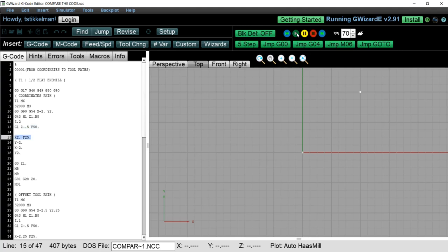Then we do an X 2 inches, so that is the first toolpath to the opposite side of the part. Then the next line, we're moving to Y minus 2 inches. We complete that move, so that would all be line center, but as we discussed before, this will undersize the part by a 1/4 inch per side, so a 1/2 inch on the overall.